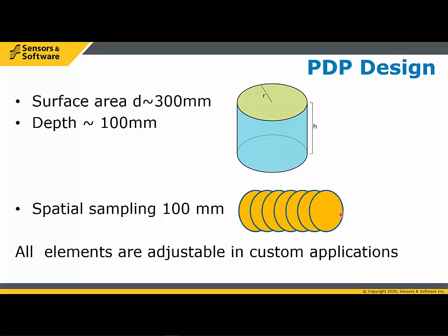So in this case, you'd want to be doing stuff at probably a half meter or less spacing, okay? If you go beyond that, then you're depending on the interpolation between the measurements, and that's as good as the variability you're dealing with. If you have a lot of variation, then you may not have a very good map. If you have a very uniform environment, then you can probably get away with it.